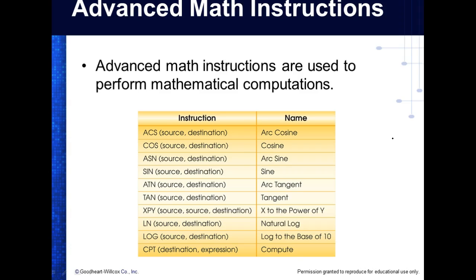So a lot of your PLCs, I don't know about the MicroLogix. The 1100 has, I think, 2 high-speed counters. I think it uses port 0 and 1 if you use it. I know the Siemens has high-speed counters on there. I think the Siemens actually has some internal timing on it too, built into the hardware of the computer. I'm not sure if it's got any hardware-based timing. So there's our math function, guys.